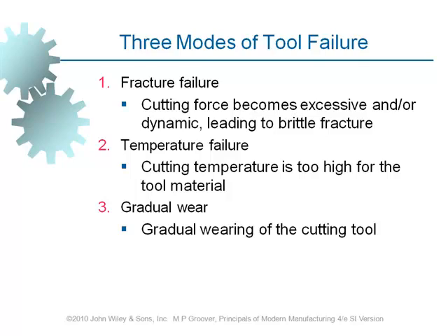Yeah, lowering the depth of cut, which is right. Lowering the depth of cut will lower the resultant cutting forces. And what else? Feed rate. Lower the feed rate, which plays the same role, because we are lowering the material removal rate.